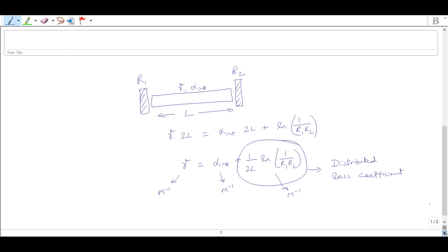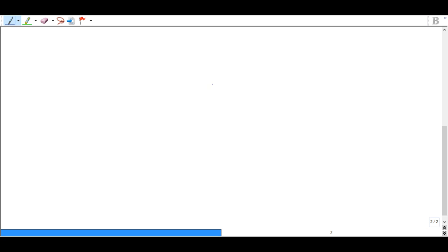So what we are talking about is, in a ring laser cavity you have the gain medium. So let's say this is the gain medium. Normally, in a free running laser, we will essentially have an isolator here so that it allows unidirectional propagation. There is some coupler here, what we call a WDM coupler, which allows you to couple the pump. And finally we take a part of the light using another coupler over here, which allows you to take out the output power.